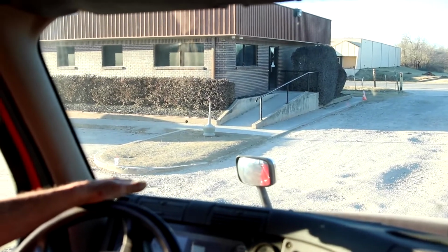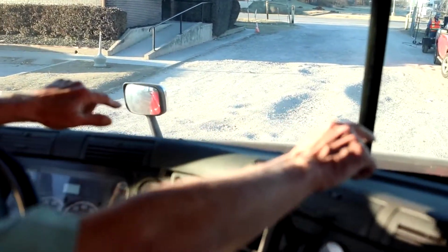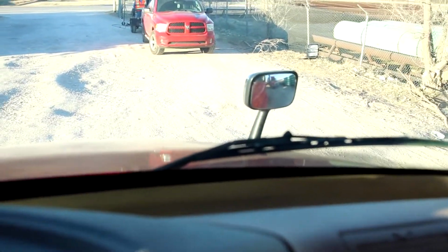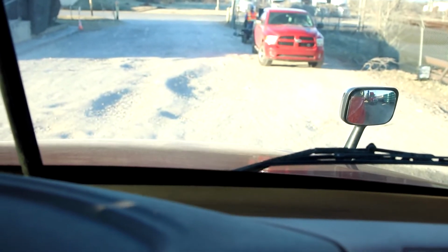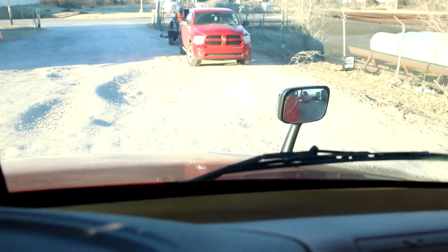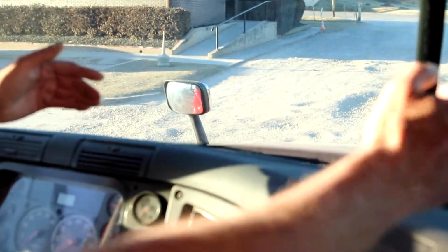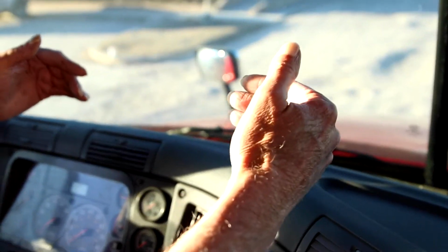has no leaks. While I'm still up here, go to my windshield wipers. They are mounted securely to the vehicle. They're not missing, damaged, or broken. And the rubber blades do not appear to be missing, damaged, or broken. And they are pressed firmly against the windshield.